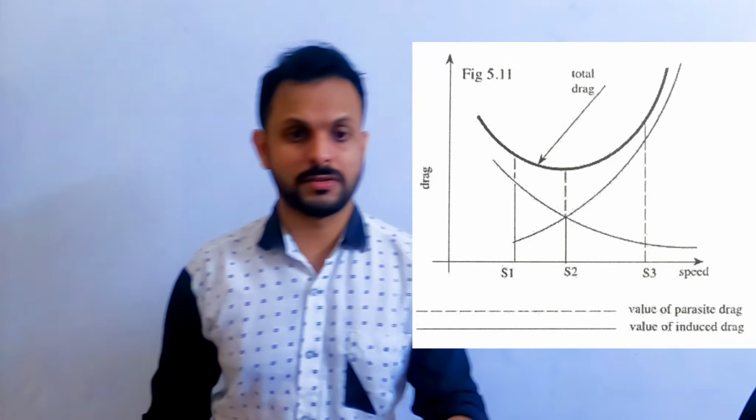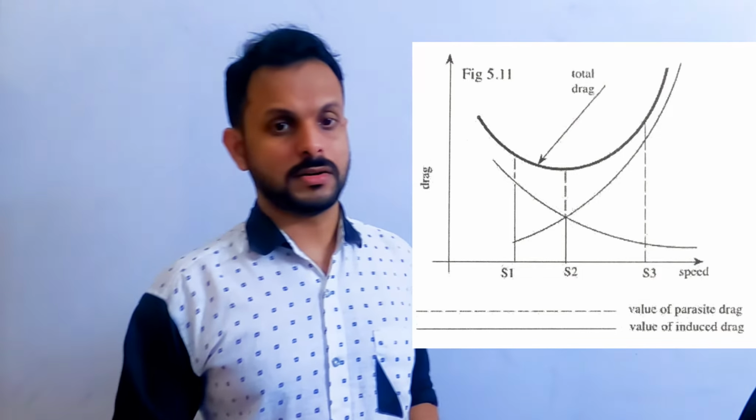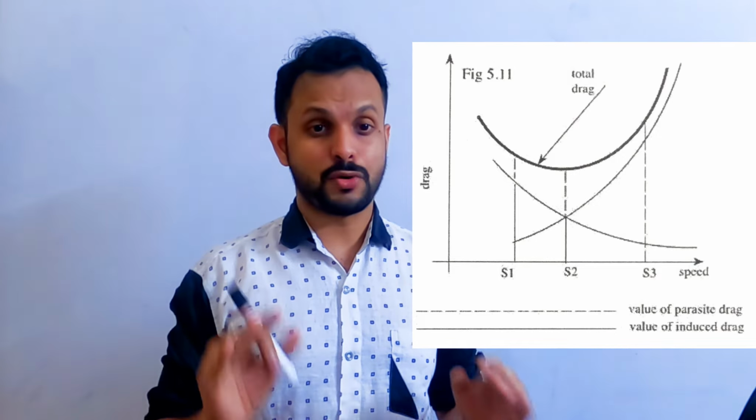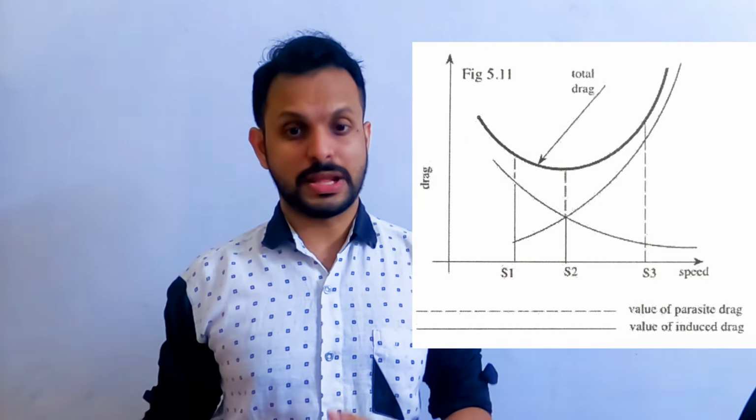We have also seen the advantages of flying at VMD. So flying at minimum drag, what is the primary advantage? Minimum drag is maximum range. This is something we have studied in the previous session. We have revised it. Let's go to question number 121 then. We have actually seen these questions before, but I'm just revising, starting a bit in between.